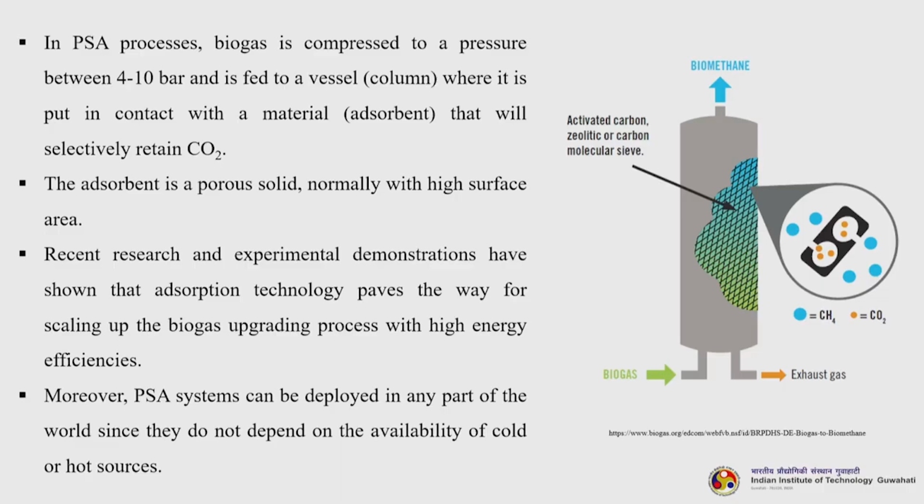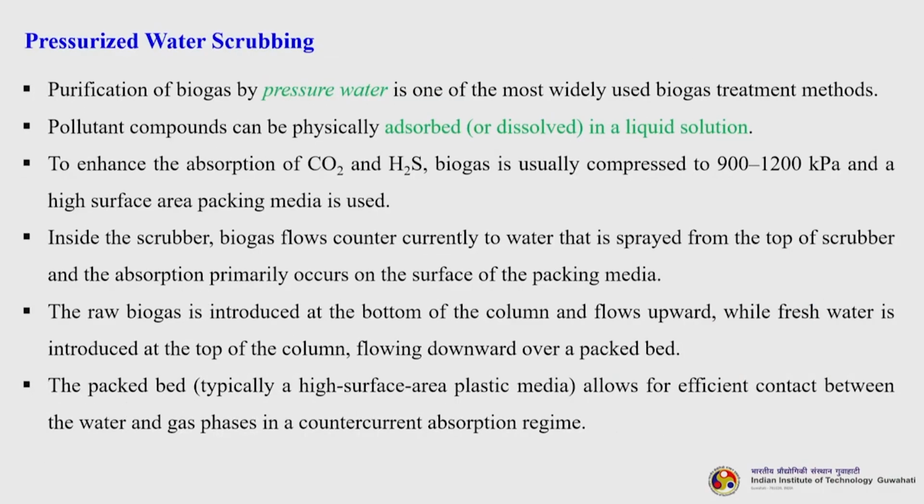Recent research and experimental demonstrations have shown that adsorption technology paves the way for scaling up the biogas upgrading process with high energy efficiencies. Moreover, PSA systems can be deployed in any part of the world, since they do not depend on the availability of cold or hot sources. And next is pressurized water scrubbing. Purification of biogas by pressurized water is one of the most widely used biogas treatment methods.